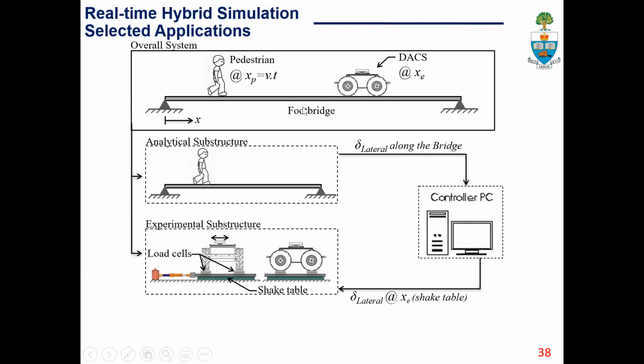In this case, we use the bridge as the analytical substructure, and we have the DAX system as the experimental substructure, and the shear type load cells will capture the load, which we will exchange between the analytical and experimental substructures. There are a few challenges that are different than previous real-time hybrid simulation applications.